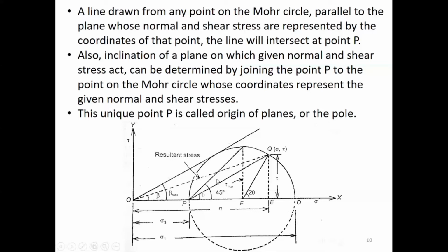So in this case, it is very simple, very easy to visualize. That's why I took the simplest problem here. Here your major principal plane is along your x-axis. Very simple problem. Keep in mind that it can be inclined at any angle for different soil conditions or cases that you're going to see later. So it can be anywhere inclined.